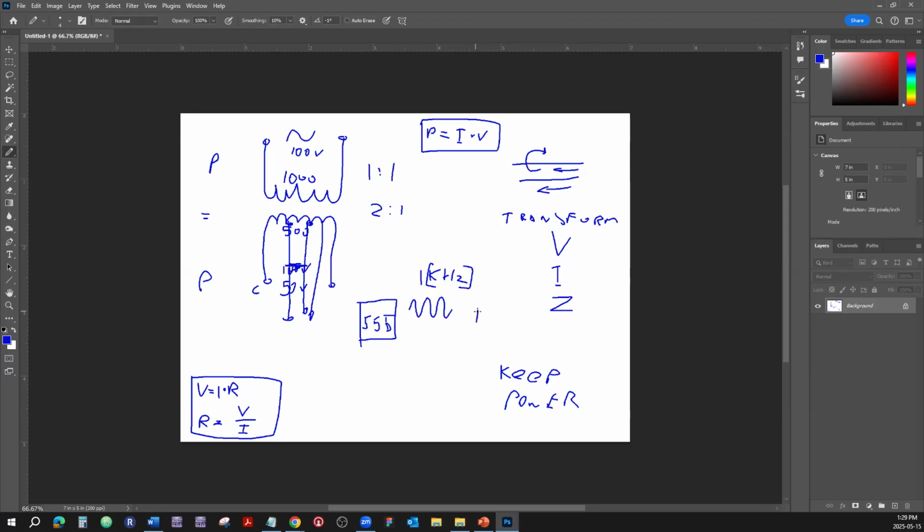And if you connect that to a tiny speaker, are you going to hear something? You have to put your ear to it. Because the output impedance of the 555 timer is significantly higher than the input impedance of the speaker. So you're not going to get the maximum power transfer, which is going to demonstrate itself as a weak sound.